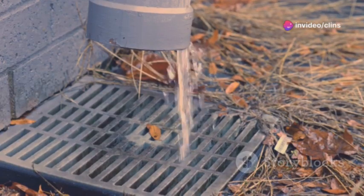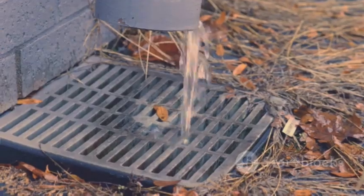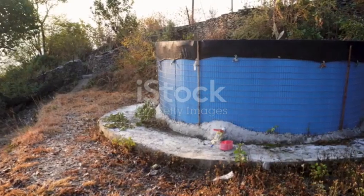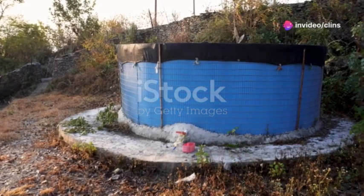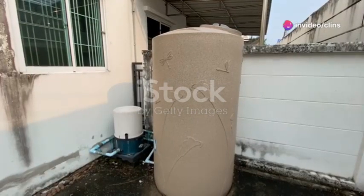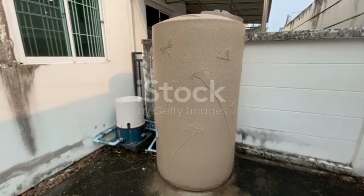Key components of rainwater harvesting systems include the catchment area, which is the surface that receives rainfall and directs it to the storage system. Gutters and downspouts are channels that convey rainwater from the catchment area to the storage or recharge system. Storage tanks are containers to store harvested rainwater for later use, and recharge pits or trenches facilitate the infiltration of harvested rainwater into the groundwater aquifer.